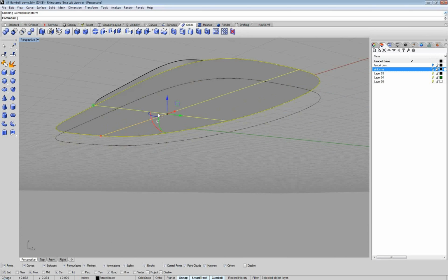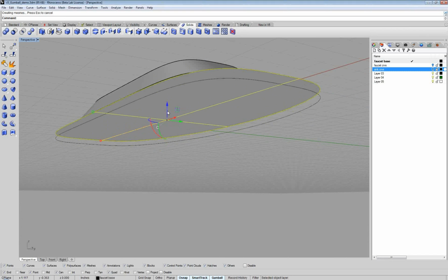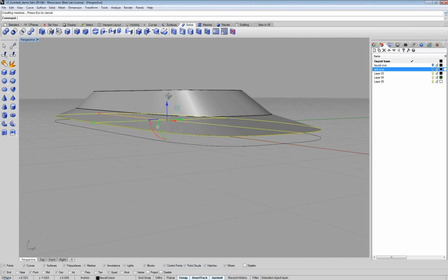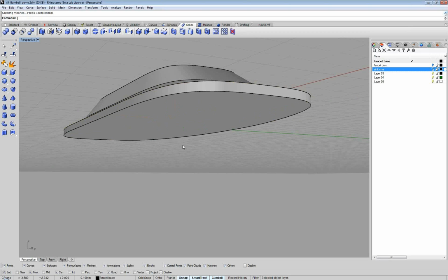And that's a little bit much, so I'll undo that. I'll do 0.1. Okay. So I just moved that up in the Z-axis, 0.1. Now say I want a straight wall extrusion coming down. I can start to translate in the Z-axis back down, straight down. But to make that a straight wall, rather than just moving that face, I'll type 0.1, and you can see 0.1 appears in the command line at this point. I'll press Enter, and now I'm limited to a 0.1 distance. I still have my finger depressed on the left mouse button. So if I hold down Control and then release, I make that straight extrusion.